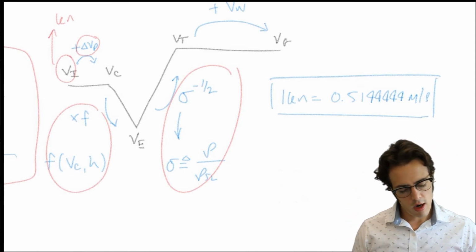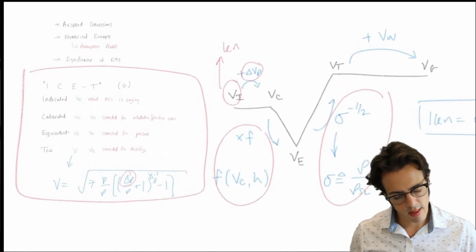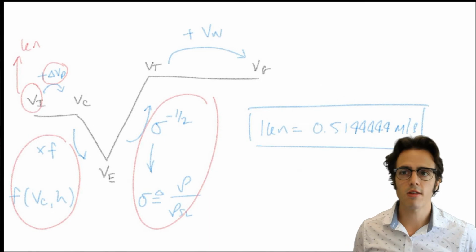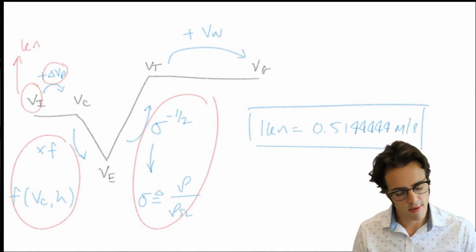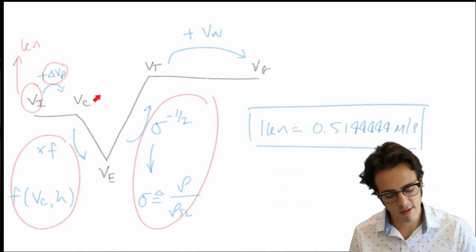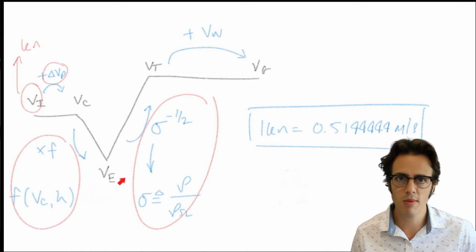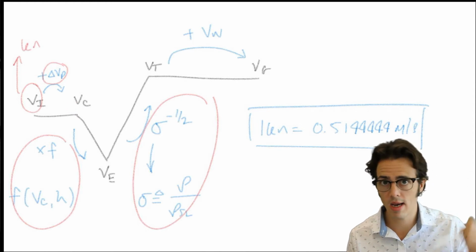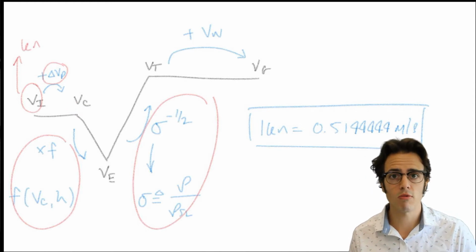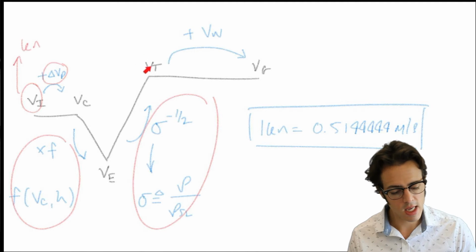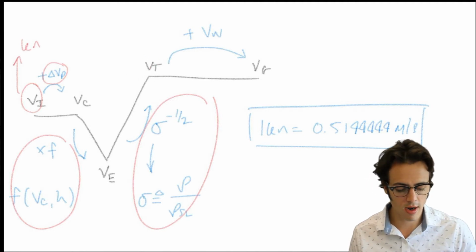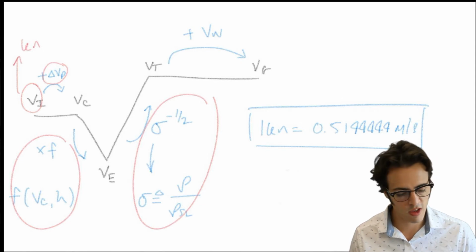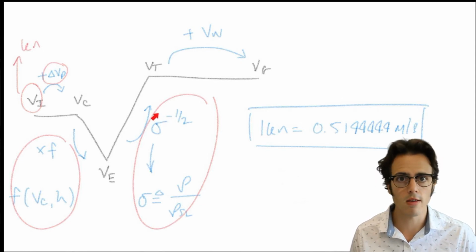So these are our corrections, and that's how we convert between these two. So remember, if you write one of these out at the start of the question, if you've got one of these to hand, then you know your respective magnitude. So if you work out an equivalent airspeed, and it's higher than your calibrated airspeed, and your aircraft is at some altitude above sea level, you've done something wrong. And similarly, if you have a true airspeed that's lower than either of these two, you've probably done something wrong in your calculation as well. You've probably forgotten that there's a minus sign here.